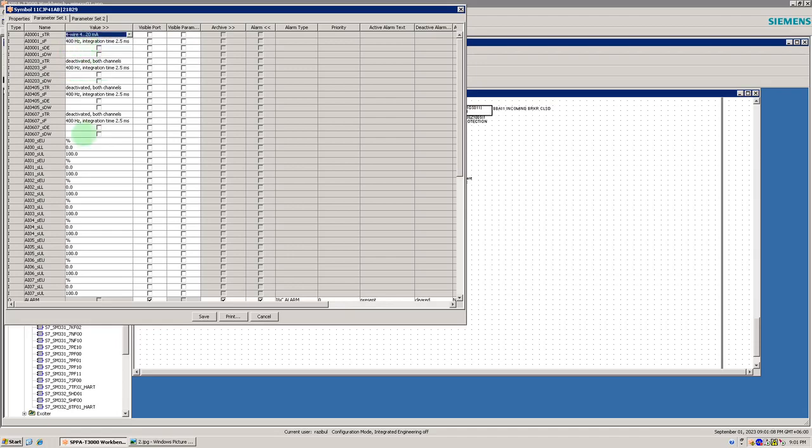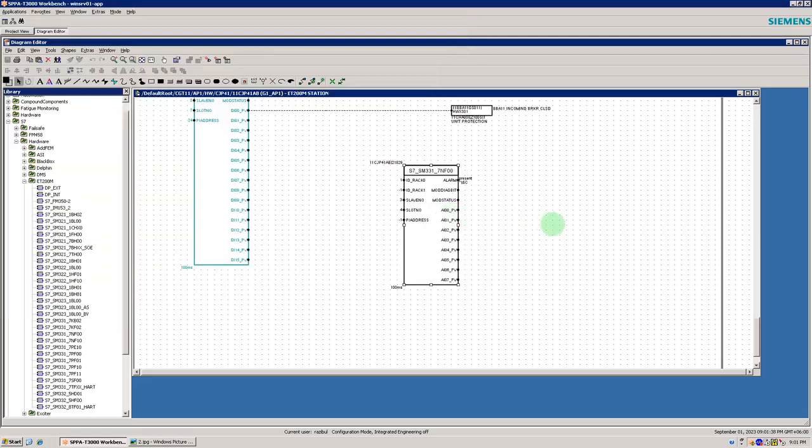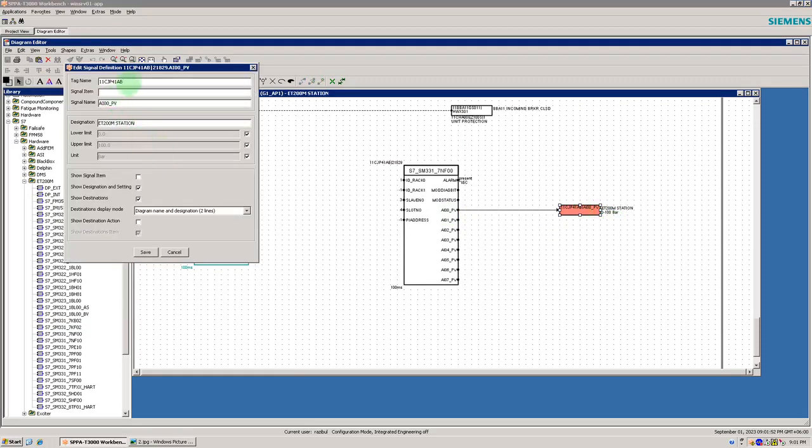Then we need to do the configuration. It will be percentage, the engineering unit, 0 to 100%, or what will be the output, like we can say if we select here pressure, and 0 to 100 bar. So the channel 0 and channel 1 will be activated at the same time. As you can see, this is 0 to 100 bar automatically, and we need to add the analog signal.